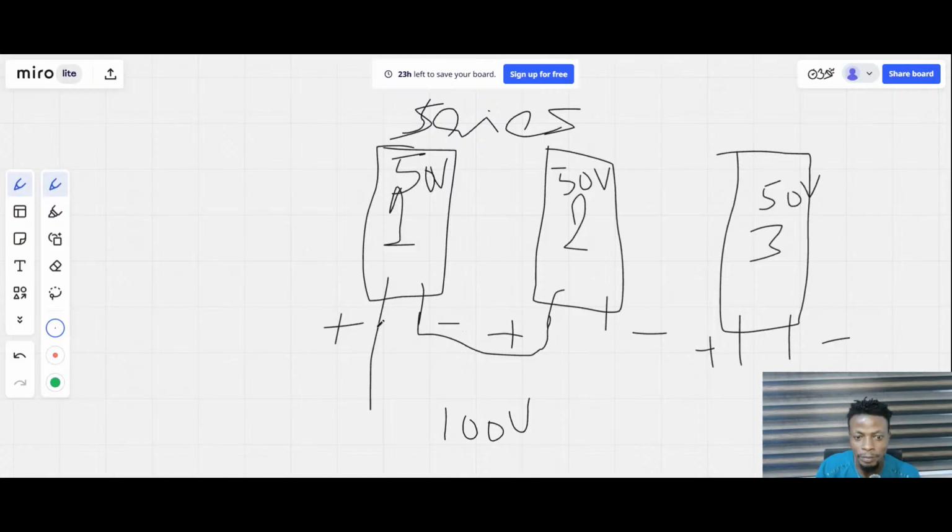So this is looking like just a single panel now, just like you have here, plus here, minus here. So in order for me to connect these panels that I've connected together to this one, I just have to take one terminal from this panel and connect it to an opposite terminal.